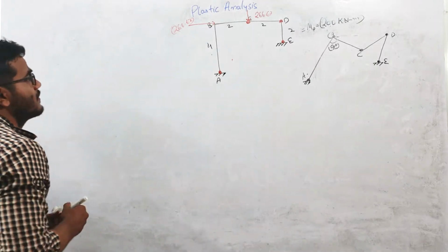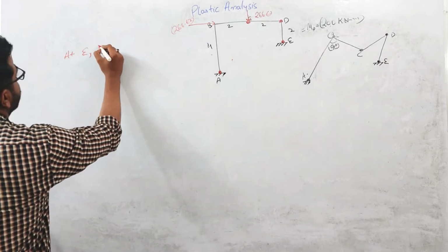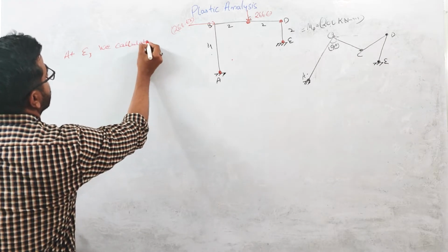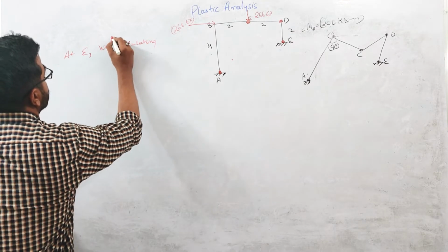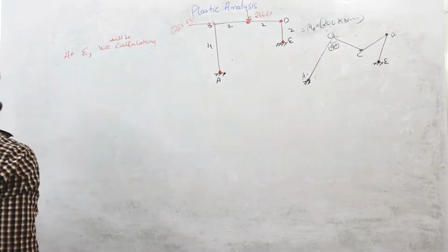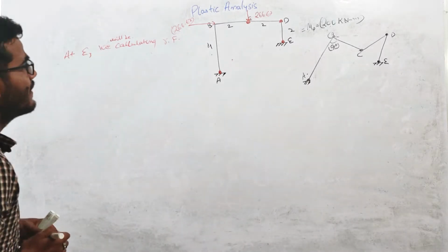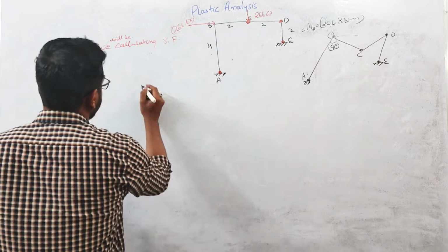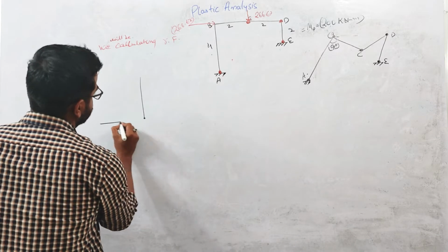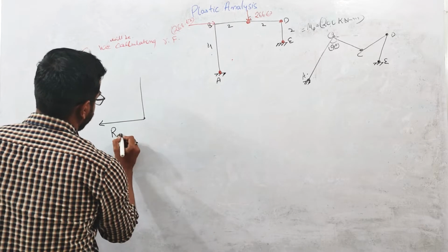So now let us come to this first E point. At E, we will be calculating the reaction forces. If you see at this E point, let us take this member DE. At this E point, let us assume this reaction force is acting in the left direction and the value is REH.